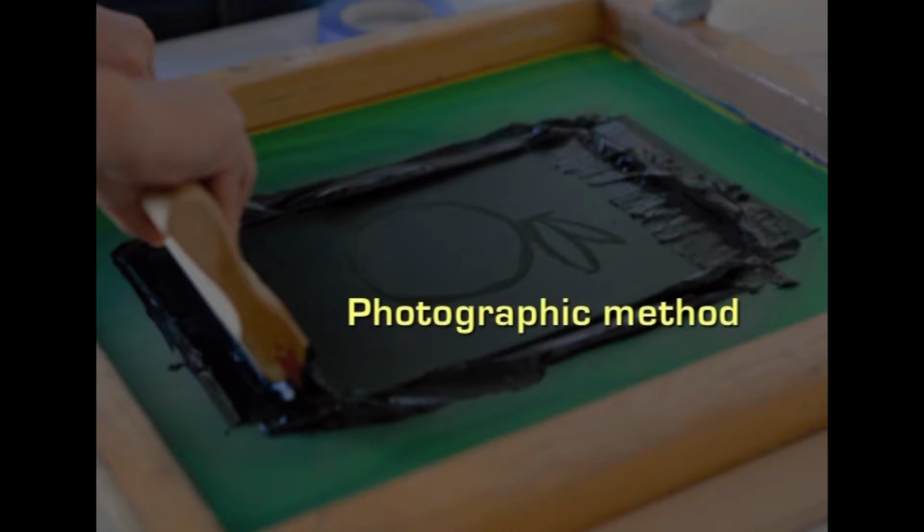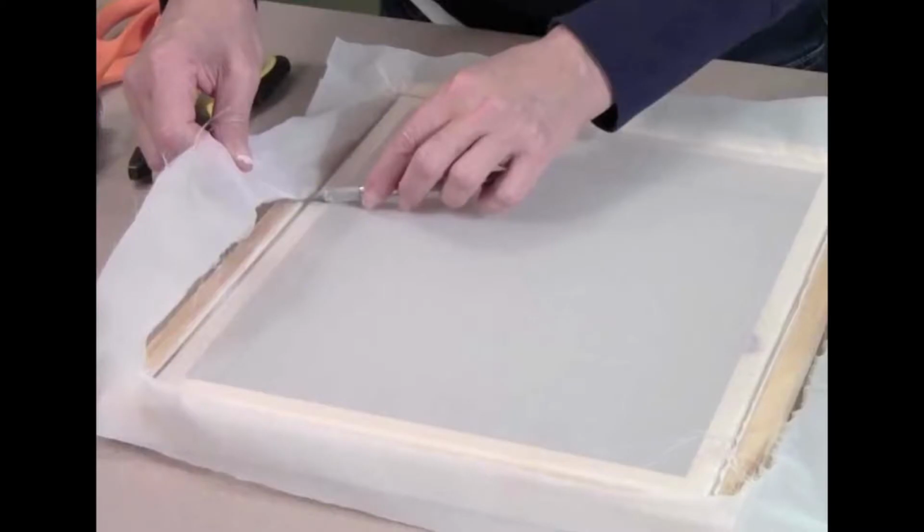Coming to the fourth method, the photographic method. Today, the design is photographed and a negative is used for producing screens. This method requires considerable experience and skill and is very widely used. Silk bolting cloth stretched on the screen frame is coated with a sensitive solution of gelatin dichromate and is dried in the dark. The portion of the design depicting one color is drawn separately on tracing paper with dense opaque black ink, which is called a positive, and is placed in contact with the sensitized screen and exposed to light for a short time.